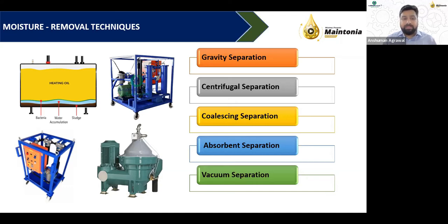So for fire resistant fluids, it might not be effective. Absorbent separation and vacuum separation. These are the technologies which are used very regularly with phosphate esters. For phosphate esters, the absorbent based separation is something which the OEMs have already provided you.